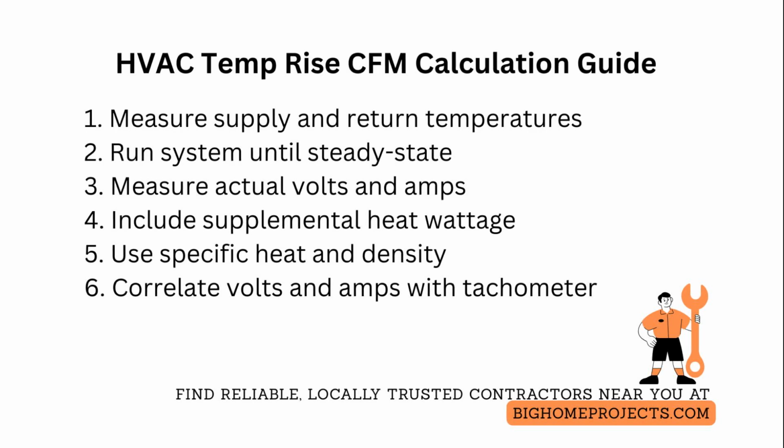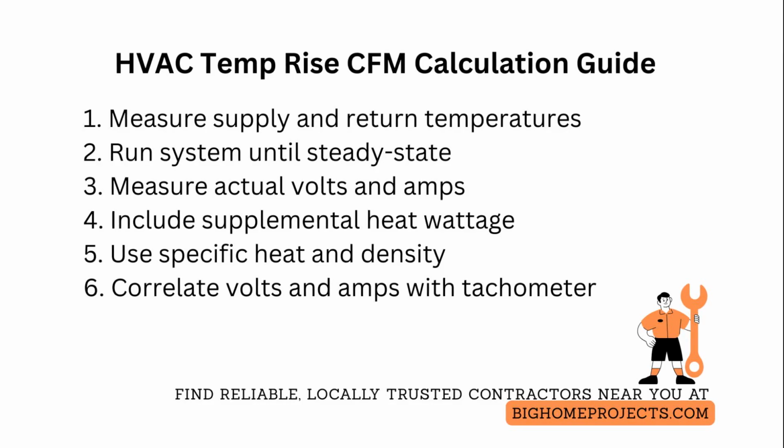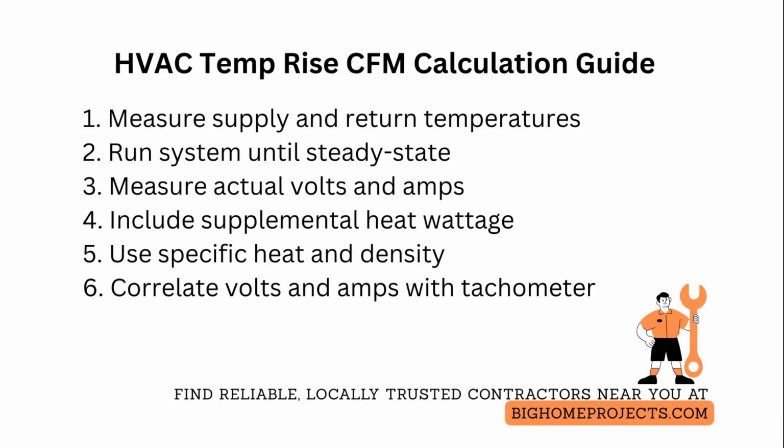If using single-phase motors, measure both legs and average only if the supply is balanced. Document every reading with timestamps and ambient conditions, and repeat the test under at least 2 operating modes to verify consistency and rule out transient errors.